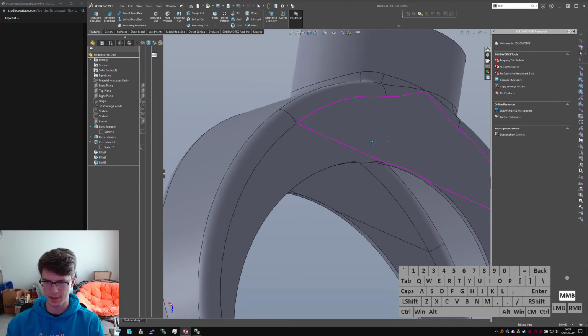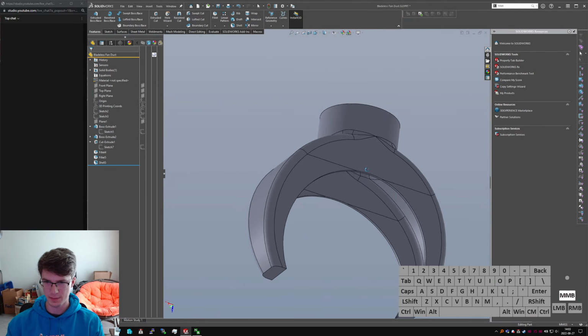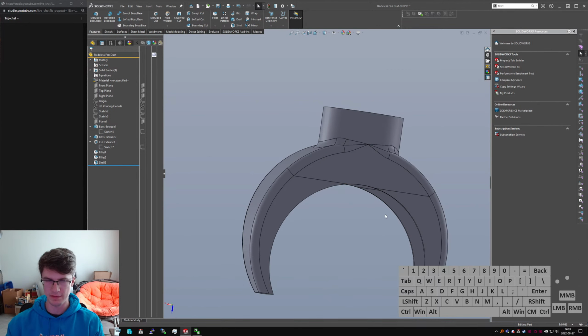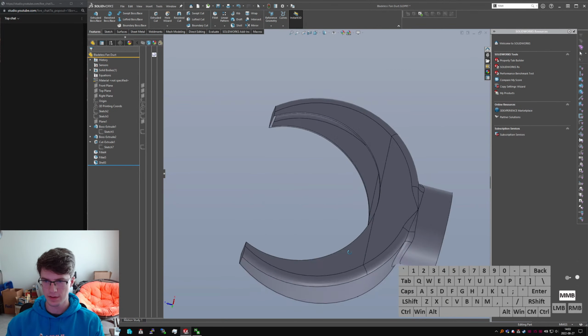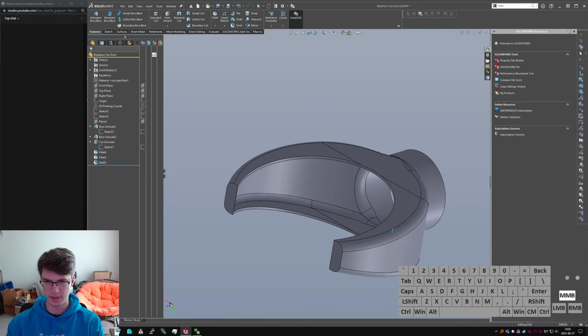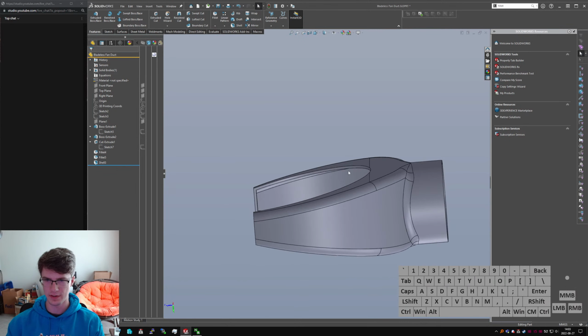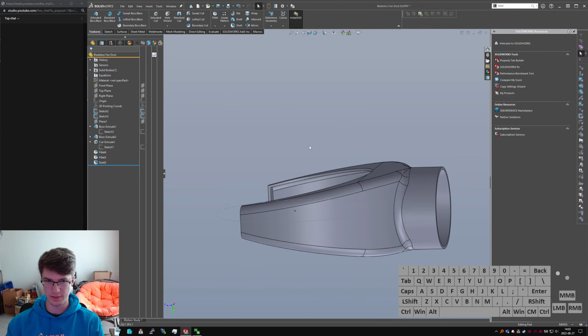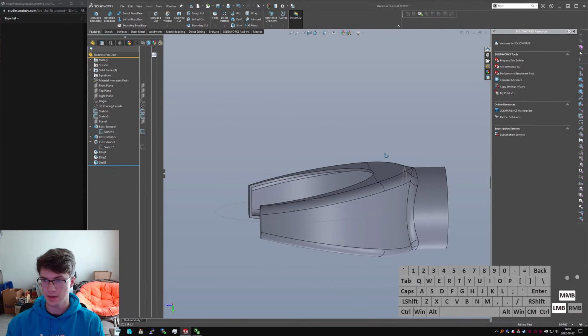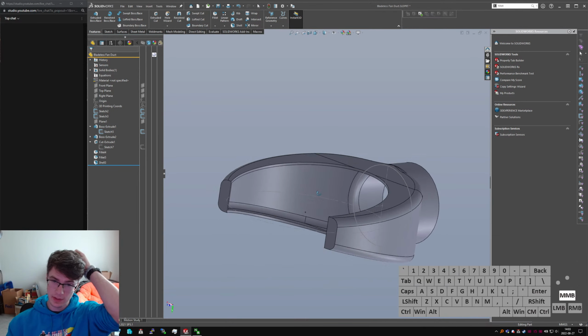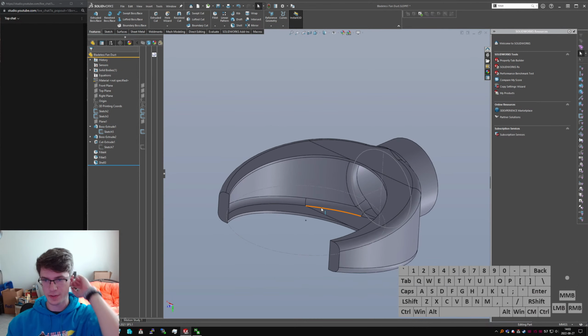I don't know when this will get printed, but I suppose if I really wanted to, I could make that flat up there and give myself a little more printability. But here's a quick duct from, you know, not much, just some idea of where you want things to end and where you want things to start. I've started doing this more now, actually, having my starting positional control features really early, and that makes it very easy to just adjust things and drag things around and say, oh, okay, these are the sketches that control the rest of the features. All the other stuff is making tweaks and modifications to that.